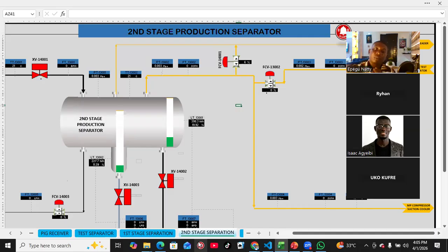And then after they must have rectified that situation, they need to reverse back to the original state of that alarm, right? Because you don't need to bypass the alarm forever, right? Bypassing the alarm forever is going to cause problems, because in the long run, you guys will take it that it's normal for the transmitter to be silenced, right? So with that, it's going to cause a situation later on. So bypassing an alarm is needed, is done, but then you need to carry out these activities before you allow for bypassing the alarm.